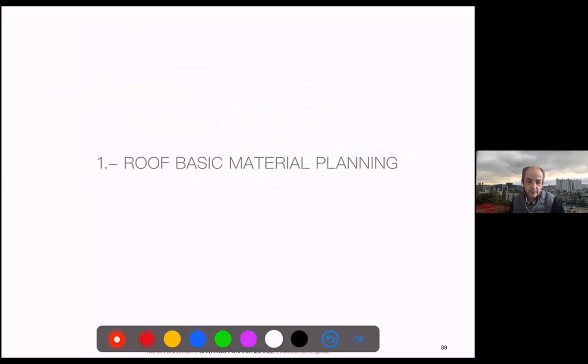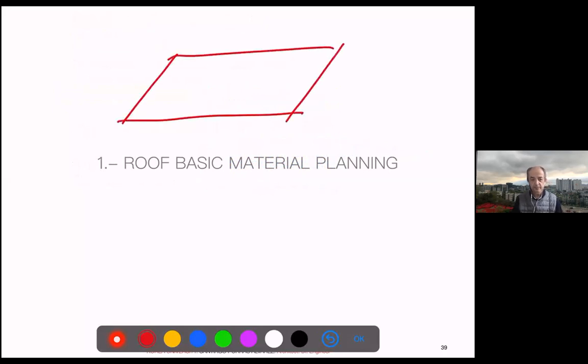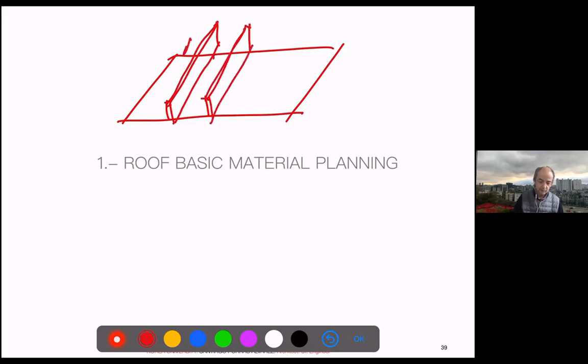There's a question over the Catalan roof. So if you have the base slab from the Catalan roof, you will make small brick walls to support that upper layer, and you will make them with the slope you need, right?